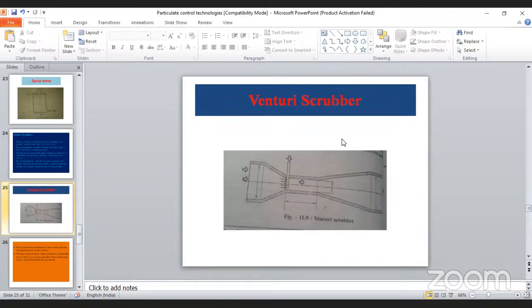When the fluid flow is less, automatically the fluid will be retained in that particular area for quite a long time. When it is retained like that, the particles will settle down, but we cannot say that all the particles can be settled in this fashion. So again, secondary treatment is required for the gas to exit into the atmosphere. For that, this Venturi scrubber coupled with the cyclone separator will be more effective to remove this type of particulate matter. Is it clear?